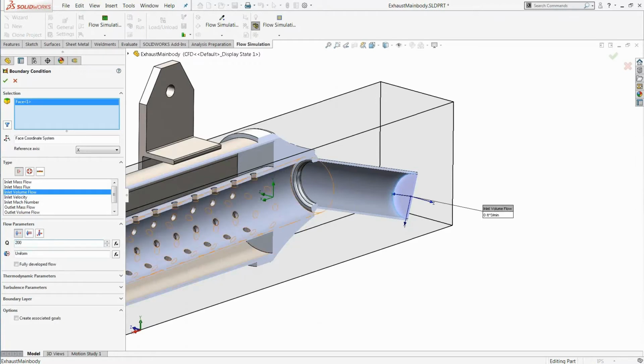And you also have a lot of control over how the velocity profile looks, where it's coming in from this boundary. I could say that there's swirl in the velocity or in the airflow. I could say it has some other vector that's not normal to the pipe. And there's also a useful checkbox called fully developed flow. And if I check that, the incoming velocity at the boundary here will automatically have a fully developed turbulent boundary layer with a parabolic velocity profile. And that would be realistic to match some existing amount of pipe that the air was already flowing through.